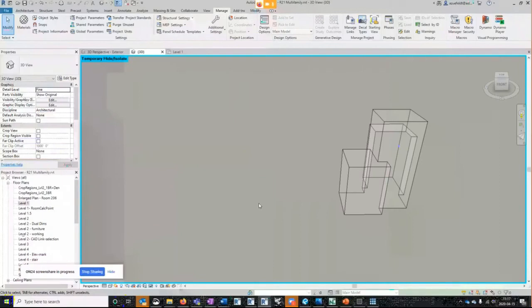I was testing out the Inventor round trip back up to Revit, and I haven't gotten to play around with it quite as much as I'd like. But my observation is that what it outputs is fairly flexible, and it will output a family, an RFA file, that you can load into Revit.